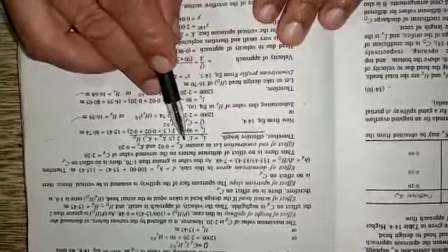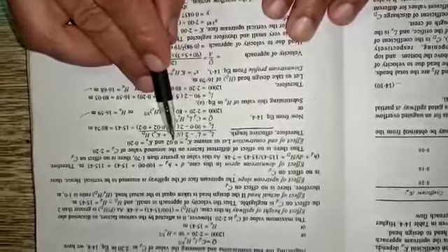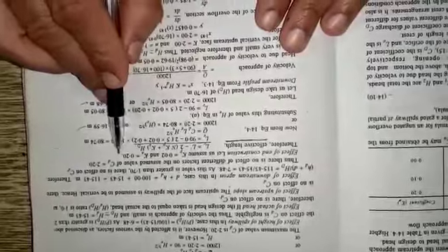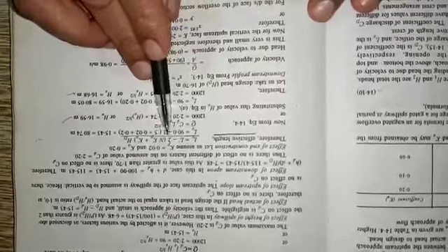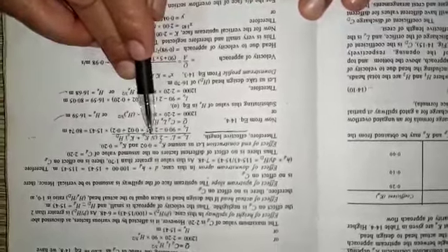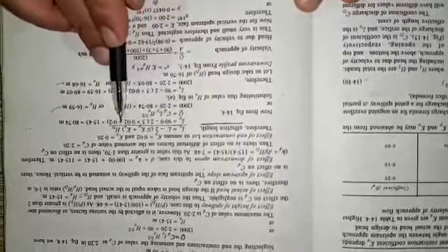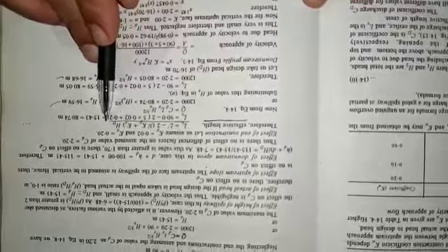Now, the end contraction coefficients: Kp for piers is assumed to be 0.02, and for abutment Ka is assumed to be 0.2, which depends upon the shape of piers and abutments, as we have discussed earlier. So, using the above data, let us calculate the effective length of the spillway using the formula LE is equal to L dash minus 2 into N times (Kp plus Ka) into HD.